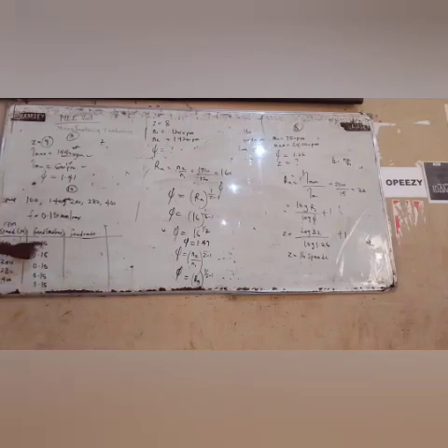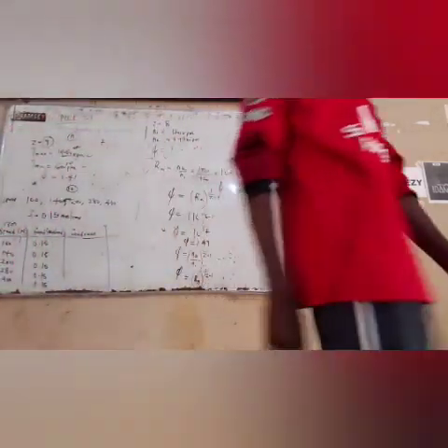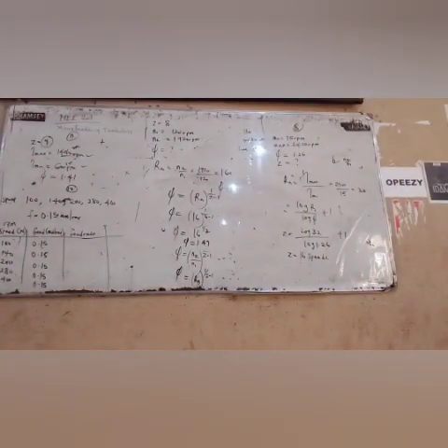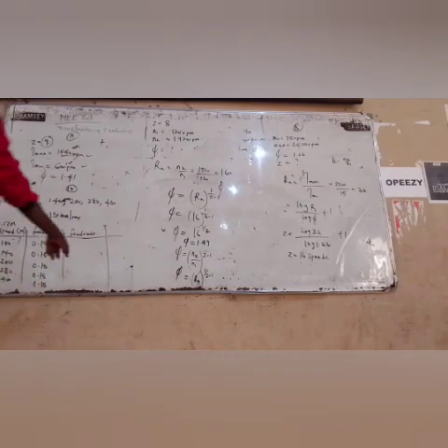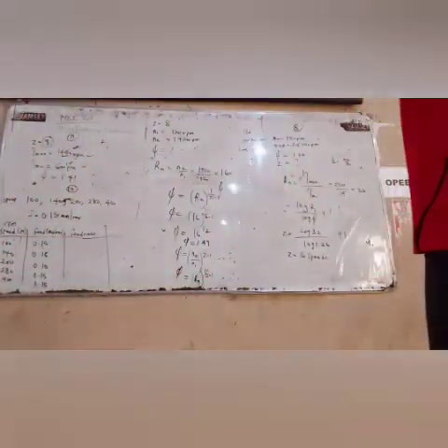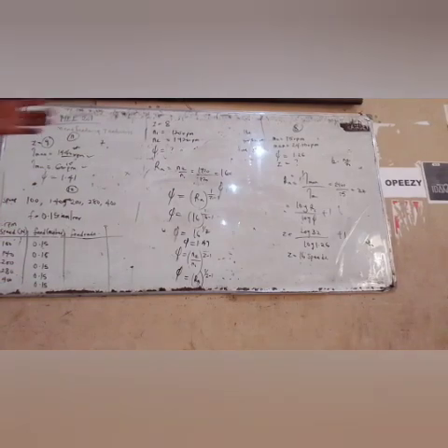No, this one is different. Speed is in RPM. This one is not speed, this one is feed, in millimeter per revolution. It's not RPM. They told you mm per minute, and this one is in mm per revolution, so no one will change it.